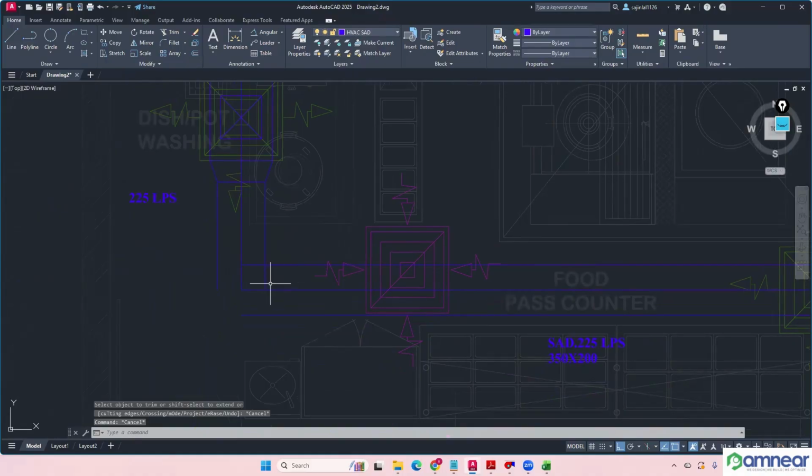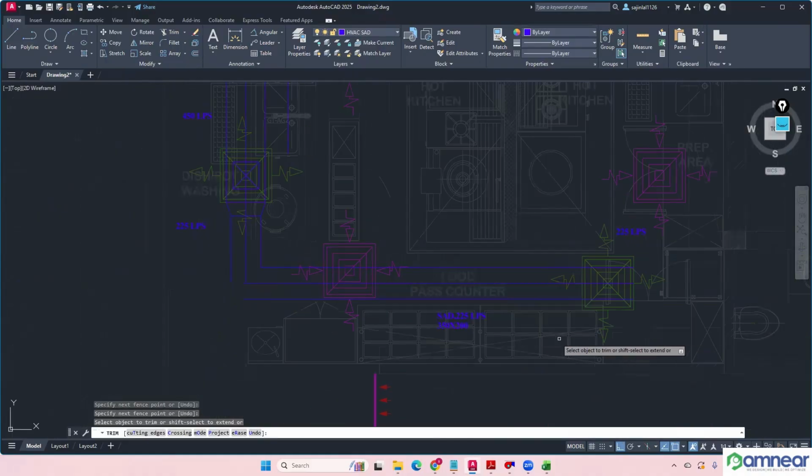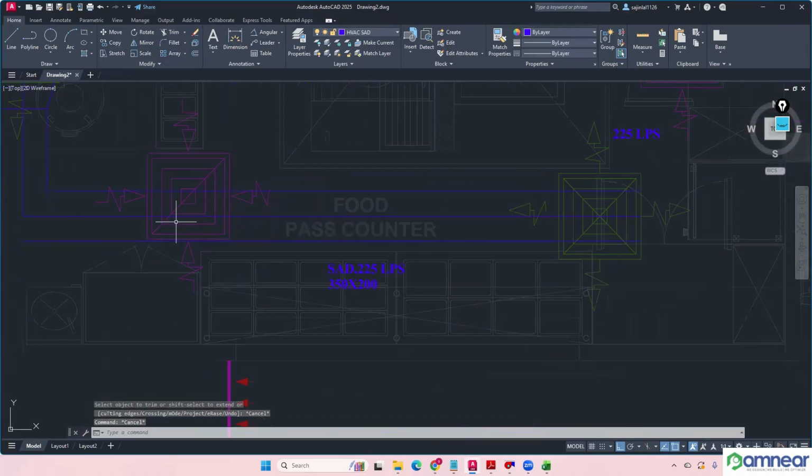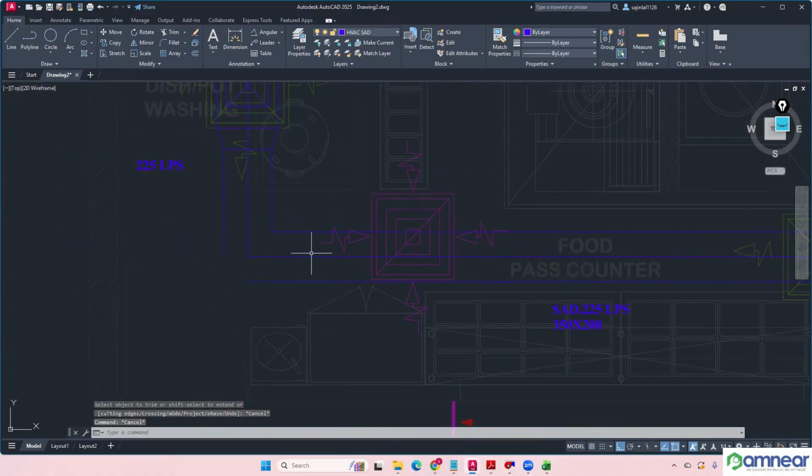Okay. Now here we need an elbow. Elbow short radius only, no? 350. So 100 mm is fine there. So F enter, R enter, 100 enter. It is not flattened. Two entities are non-coplanar, so that's why it has to be flattened. So FLA flatten enter.